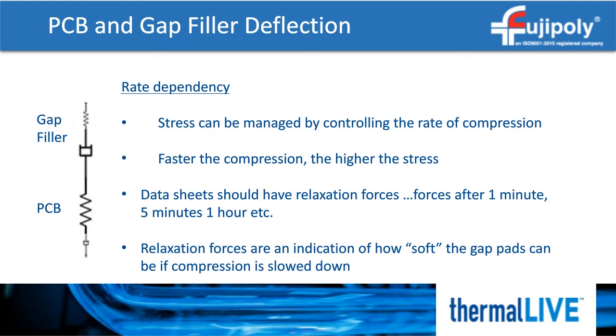Gap filler materials usually are not highly elastic relative to the rate dependency component. In fact, if you take a viscoelastic gap filler and compress it with your fingers, you'll see it will slowly return to its original shape over time, but that may take several minutes. Putty pads, on the other hand, won't bounce back and are more viscoplastic than viscoelastic. Either way, they will still have a rate dependency, and a putty pad that is compressed quickly will be difficult to differentiate from a non-putty pad.